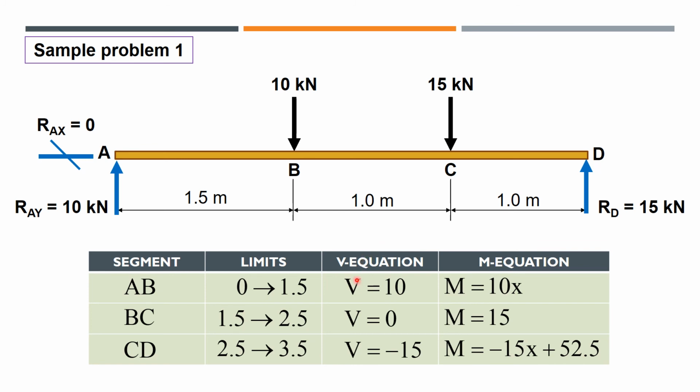The unit of each shear value is in kilonewtons. And for the moment, ang unit naman dito ay kilonewton meter. So we will use these shear and moment equations to draw the shear and moment diagrams by substituting different values of x using the limits for each segment.